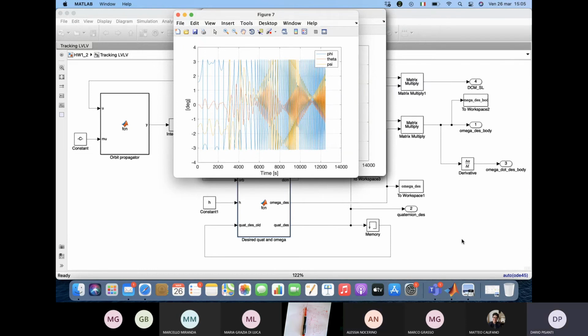Sorry, Professor, just one thing that probably I misunderstood. Why, for instance in the initialize file, don't we initialize the attitude in terms of error angles, that are much easier to visualize, and then convert them into quaternions with a built-in function like angle to quat or something like that? It's just to select a proper initial condition. I don't know if it will solve the problem. Yeah, it's another way. You can definitely try. I think if things are done correctly with the DCMs and quaternions, it should work. Give it a try.